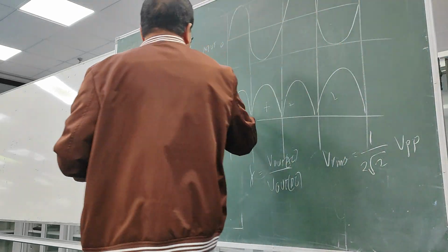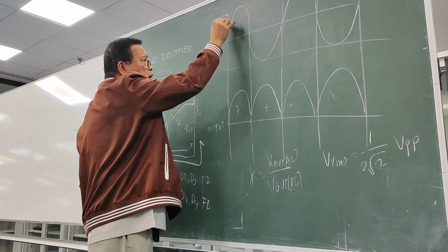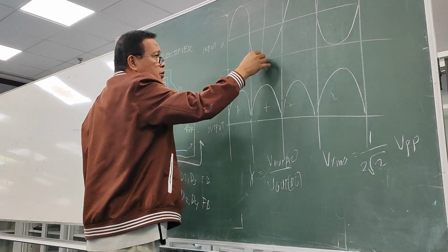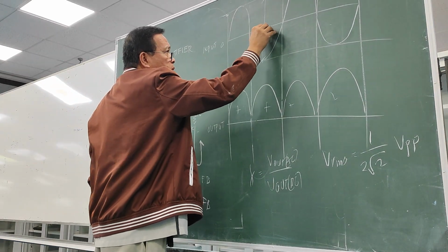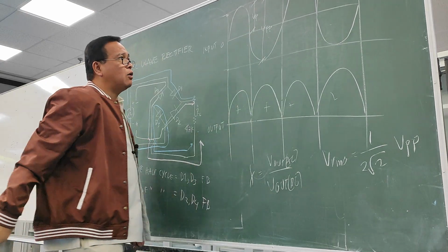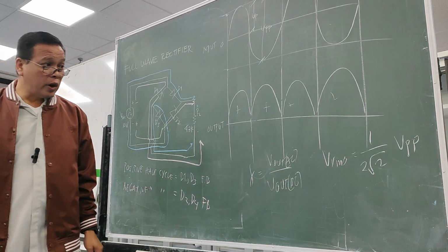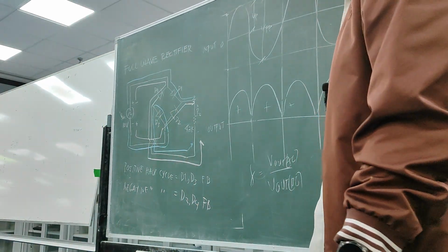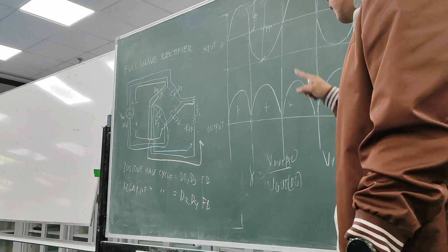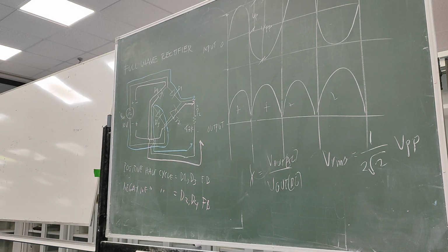Peak to peak values are measured from this point until that point, while this one is what we call peak only. That's why when you calculate the VRMS using V peak to peak values, the VRMS value is the one that you measure with the DMM, the first column on the table.